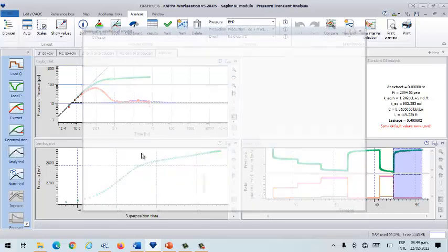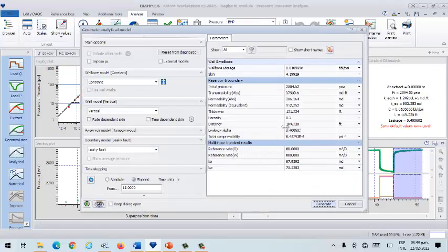So then you go and you try now, you already got an idea of what the distance to the leaky fault is, because as a good tool, Sapphire helps. If you don't have that tool, then you can do it as I was doing years ago, but that means that you have to be trained. So I'm like machine learning, I'm a human learning. Maybe over the years, I saw the signature. I may have an idea of what that is, I mean, if it is a radial or if it is a leakage fault.